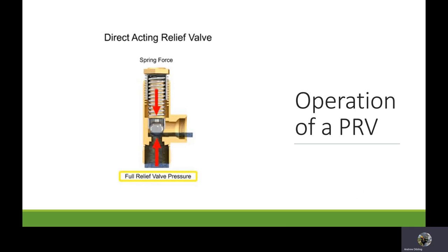Now here's a little graphics image file that shows you how the system works. You have the spring force pushing down and the full valve relief pressure pushing up. Now on this one is a ball valve, same kind of idea as the poppet. Ball valves are used generally on very low system pressures, simple systems, ball bearing on a spring, similar to a check valve. Once you overcome that, it allows it to flow. I think of them as check valves with really, really tough springs in them.